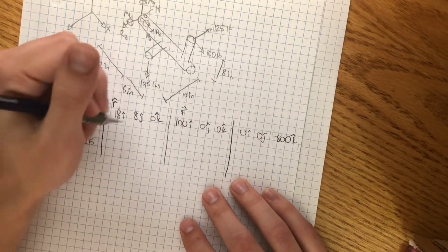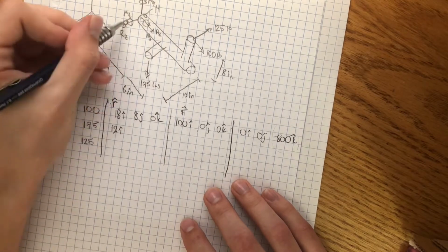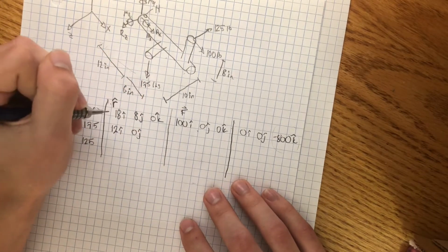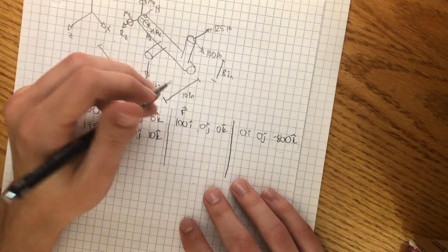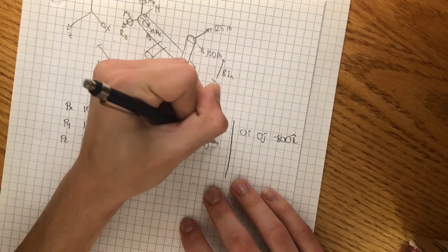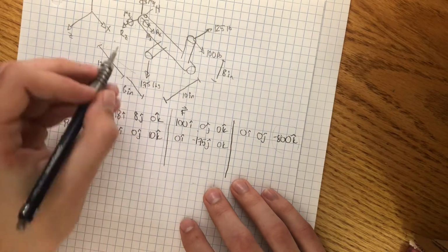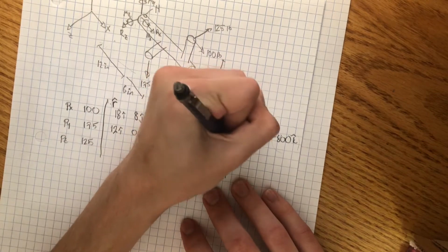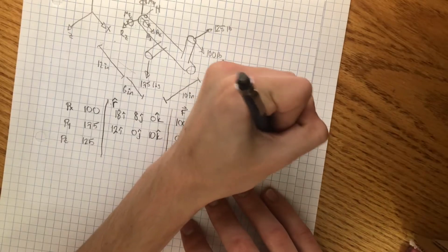And then we have 12i for 175, right? So 12 down, and 0j, and 10k, because it's over 10 inches here. Then we know that that is 0i, negative 175j, and 0k, because that's the force. 175 down the y-axis, I'm sorry. And then the cross product of that gives you 1750i, 0j, and negative 2100k.